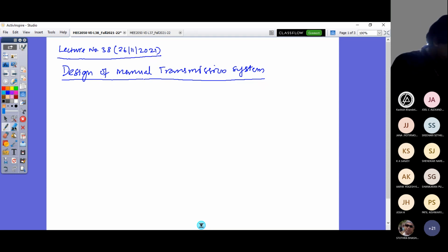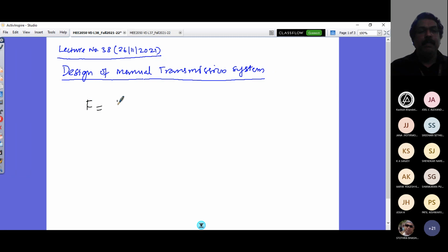The one formula is the engine tractive effort that is being provided by your power plant, the engine. Tractive effort is provided by engine torque, capital M subscript E refers to engine torque, and epsilon naught refers to the overall reduction ratio of the transmission, including both the gearbox and drive axle gear ratios.